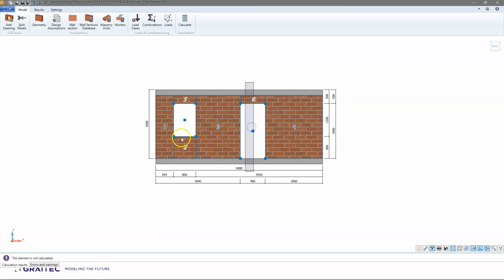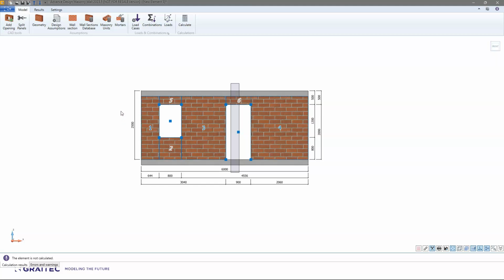And please notice that at this moment, it's very similar to what we've seen on advanced design. You have 3 design panels and also some that are not considered in the design, but the efforts are distributed to the neighboring panels. In advanced design, it was done using strips. So we integrated internal FEM forces into the integrated resultant forces. But right now, we will simply just take the loading and distribute it on 3 design panels.